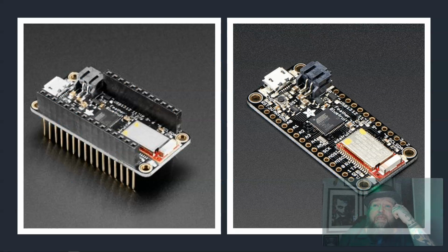Versus other things like this being Adafruit. Adafruit is a company that you can look up that does a lot of stuff right now with Arduinos and has their own devices, but these are called feathers. Feather being like they're thinner and narrower, and there's a whole family of things that they provide, but we still have things like these pins. You have things that allow for Bluetooth and other connections. You have connections here so you can hook up lithium polymer batteries and have other power sources directly, and usually these boards like the feathers are designed so they'll also charge those batteries for you. So if you want to have something that runs off batteries and is rechargeable and you don't want to buy external boards to deal with that, they have them in here.